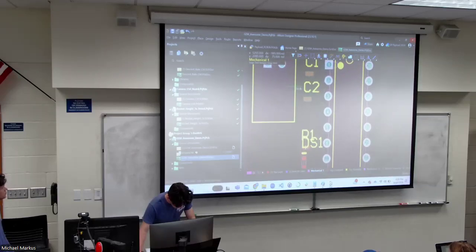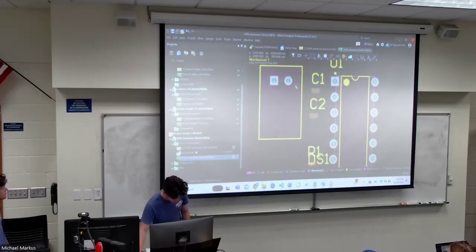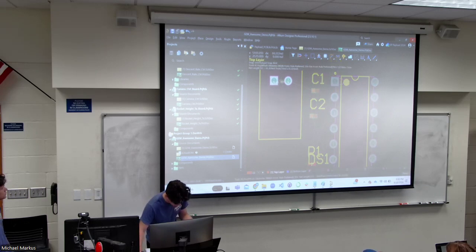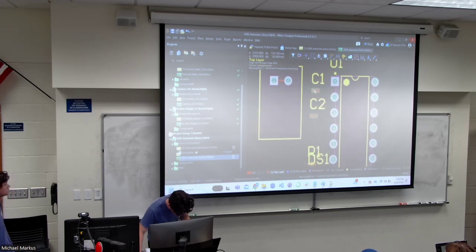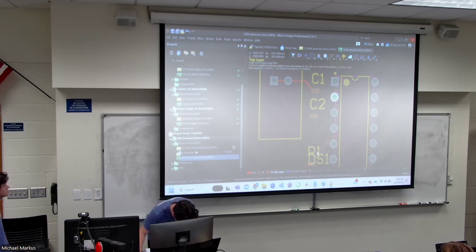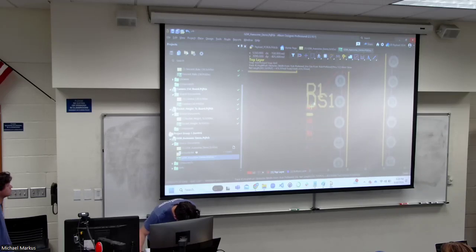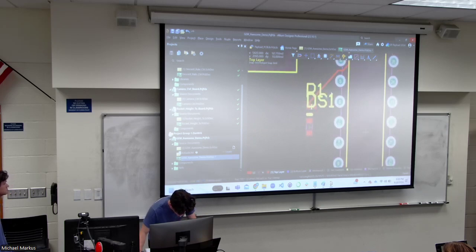Once you're there, if you zoom in, you can see the different nets of your parts. If you click in the middle of a pin, it brings up your ability to route, and it will do its best to route to that location for you. There's some degree of auto routing here. I'm going from 5 volts to 5 volts since that's a net. I want them to be connected. Then I can keep doing that between all my nets, or like if I want LED output to LED output, that's going to be to this net, and you can sort of do your best for that.